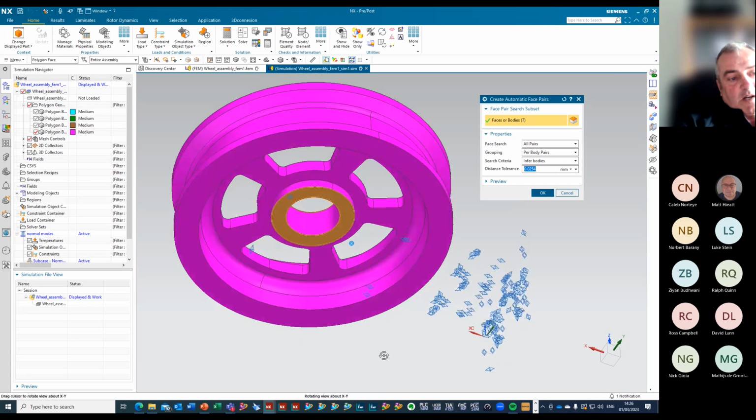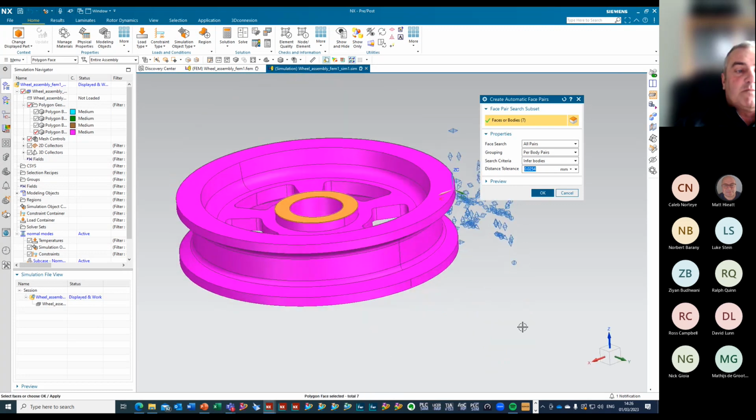Take all of the surfaces that I'm interested in. So what I'm saying here is I'm choosing all of the surfaces that I want to consider to glue together. If I just took everything, then I would start to glue these internal cylindrical shafts together, which I might not want to do. So here I'm just being specific. And again, I'll show you in the PowerPoint what I do. So here you can see it.